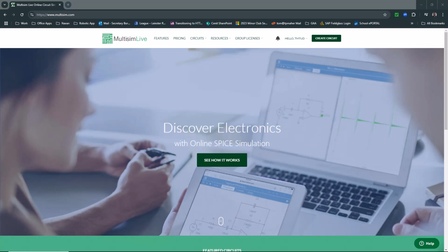So if we're looking at a motor or a contactor or whatever the component might be, we're just going to build a circuit that takes the component and represents it as a resistor and an inductor. Okay, so firstly we're going to grab some values. These are the values that we're going to use to build our circuit.